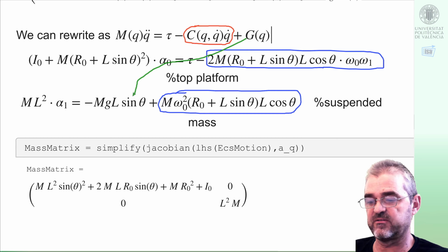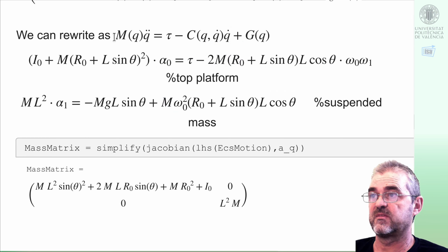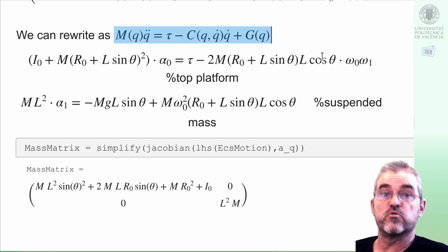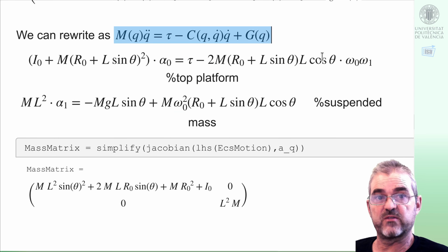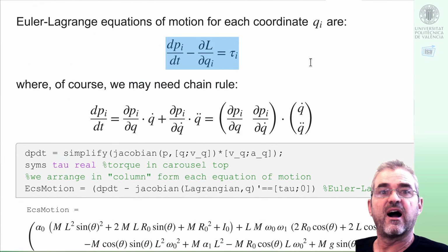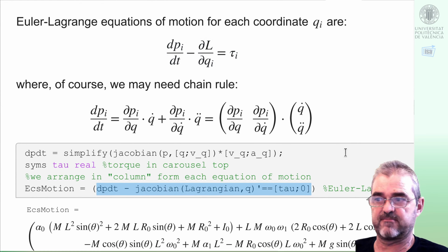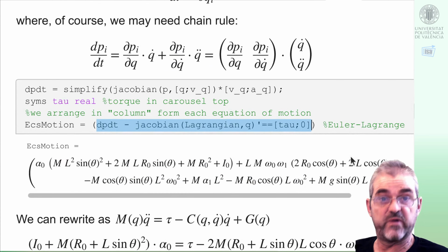So the combination of all these are the equations of motion, but of course this is just a usual way of writing them so that we can interpret them as equivalent inertia or whatever. But Euler Lagrange say that independently of how you later rearrange this, the kinetic and potential energies define the equations of movement if you write this, i.e. this. So we end with this.